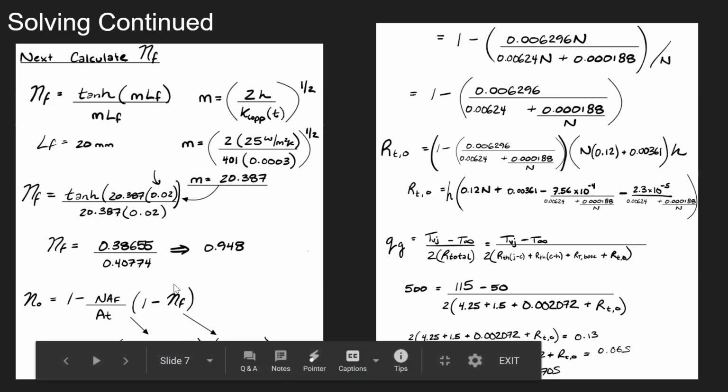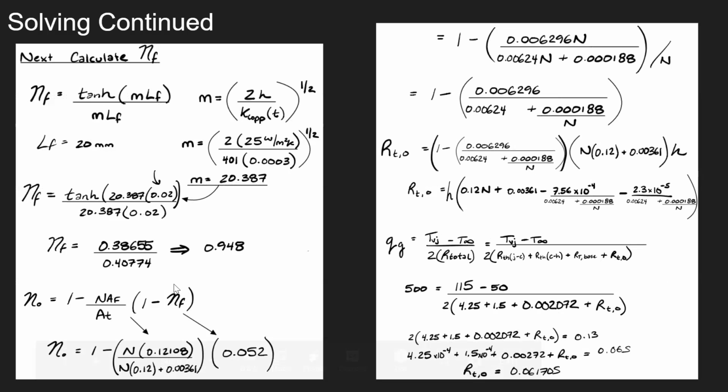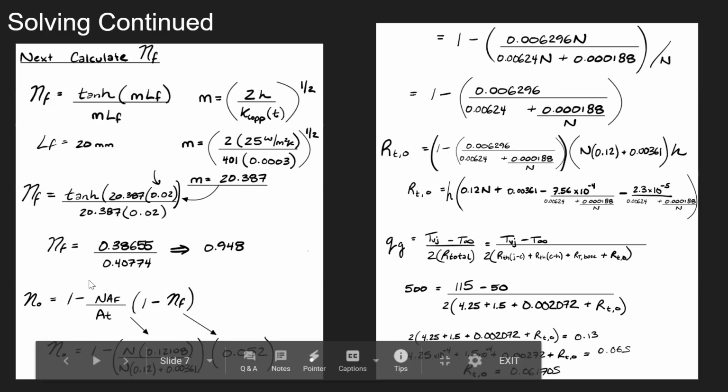After calculating both of these values, we finally had the information we needed to solve for the final resistance. To do this, we used the thermal resistance equation using temperature variation between the source and the ambient temperature, and the work above shows how we were able to find the final resistance needed before moving on to the fin equations, where we could solve for the number of fins algebraically and then in the end graphically.